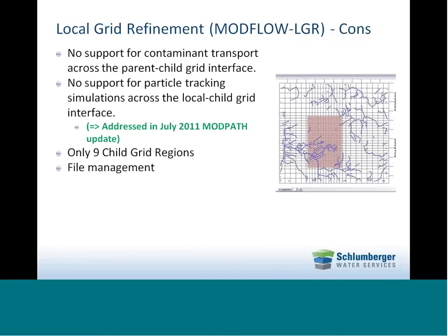Some of the drawbacks or disadvantages of Modflow LGR are that there's no support for contaminant transport across the parent-child grid interface, and that was the last time I checked. I'm not aware of any updates to MT3DMS or the other transport codes that support that. Up until last year, there was no support for particle tracking across the parent and child grid interface, but that was addressed in an update to ModPath, which was released last year. So that's something that we'll work on in the near future.